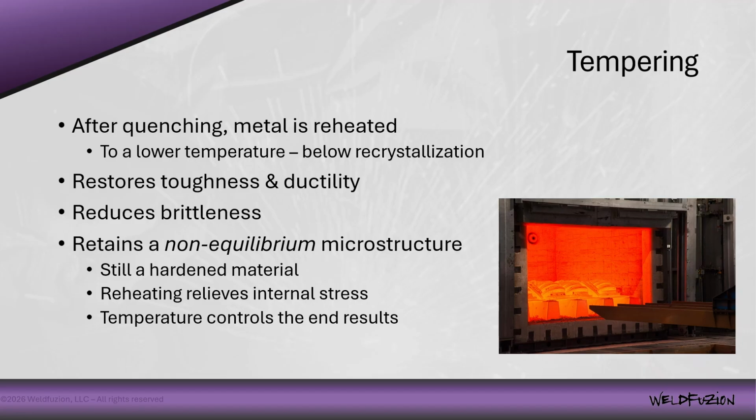It also may help to relieve some of the internal stresses that were caused by welding and then heat treating or other processing that was done. And again, temperature is going to control the results. So the higher the temperature and the longer the time, the more softening will occur.